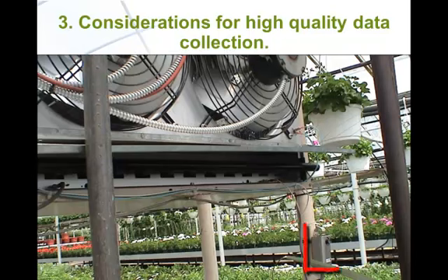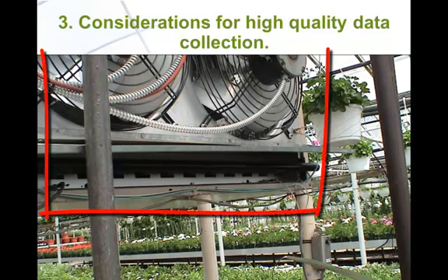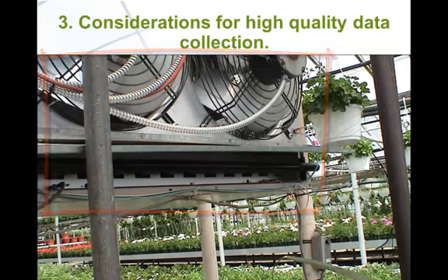In this picture, you can see a thermostat very near a heating unit. This is not good, as the thermostat will monitor heater temperature and not the plant canopy temperature. Residual heat radiation from the heater after it is turned off will keep the thermostat warm longer than the rest of the greenhouse.